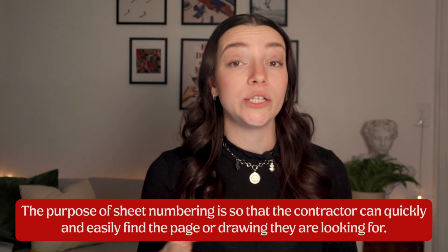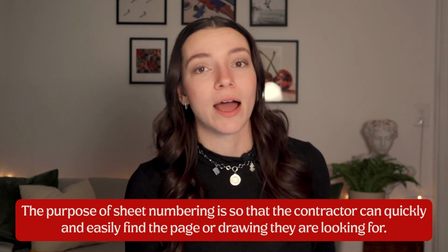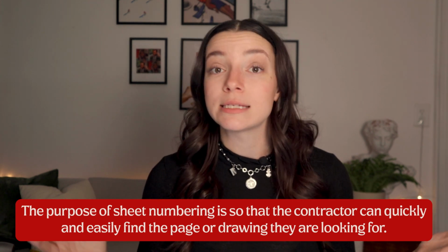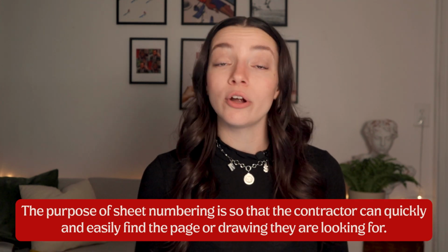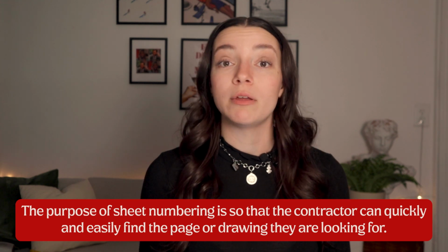In terms of numbering, again, I'm going to say this for the millionth time, it's up to your preference, but you can either separate these into separate A numbers, like A3 for finish plans, A4 for elevations, A5 for sections and details, or if you wanted to continue with the construction naming, you could do that as well. These sheet names are really so that the set is easy to read and pages are easy to find. So as long as the numbering system makes clear and everything's in order, it's easy for the contractor to flip through them and find what they're looking for quickly. That's really what's important here.